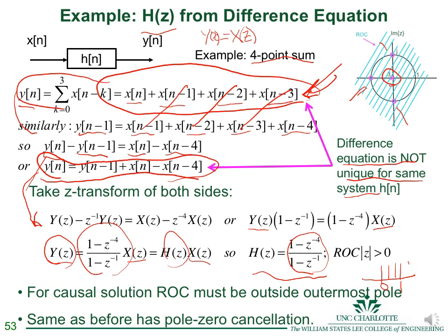And so in this form of the transfer function, we replace the z's with 1. We can see that the response H of z is going to be 4 at z equals 1. So the DC response is easiest to see if we take the z transform of the equation we started with. And so here we can say the DC response is 4 for this system.